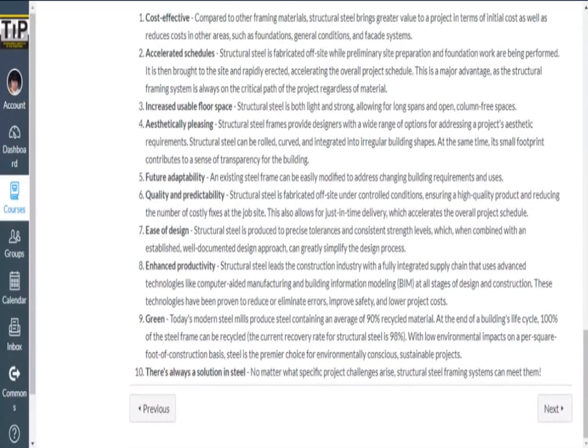In concrete, you need to test the concrete that you pour every now and then. And again, the properties of concrete may vary depending on the actual site conditions. That's why concrete is a lot harder to quality control than structural steel.